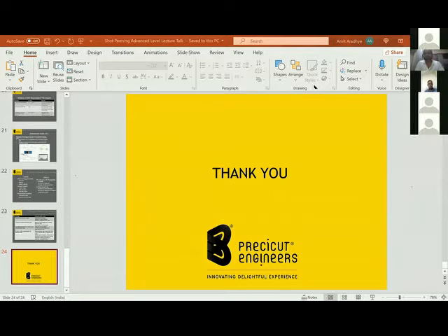Because when I say that you can induce compressive stresses as much as 50 to 60% of the yield stress, at the same time you have to look at the component geometry also, because maybe some geometry might get damaged. You will see plastic deformation in those areas, or maybe the roughness increases, which is not desired. So even these factors need to be taken into consideration.